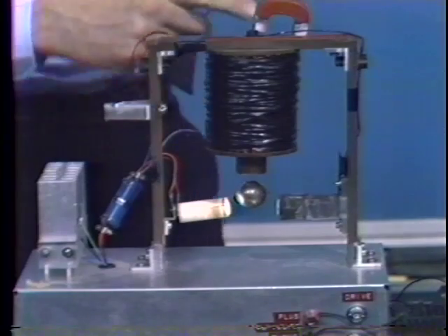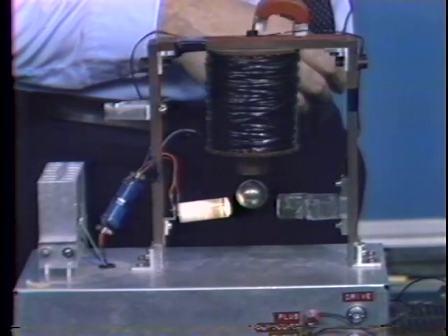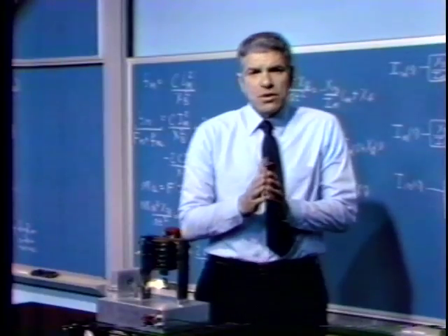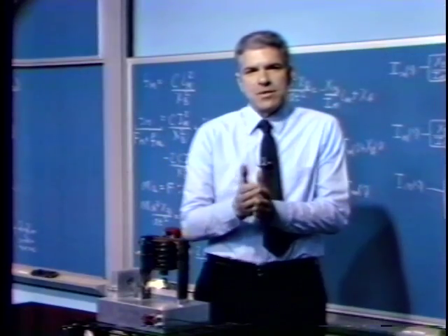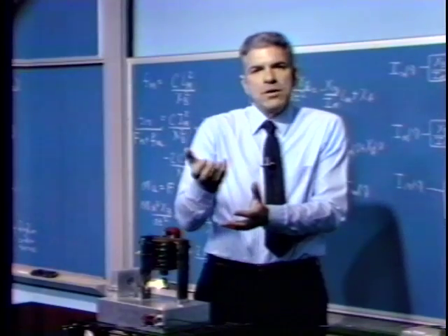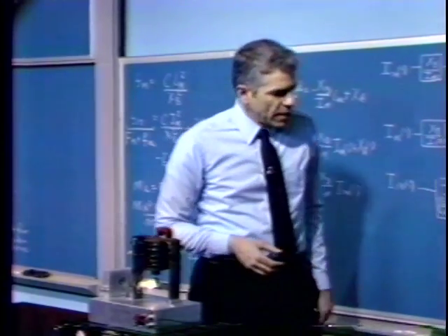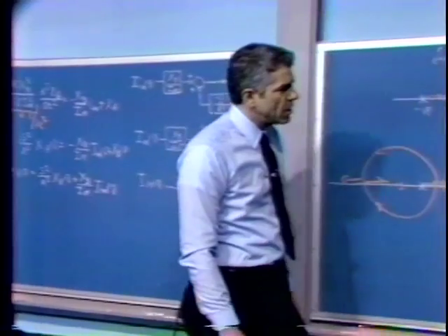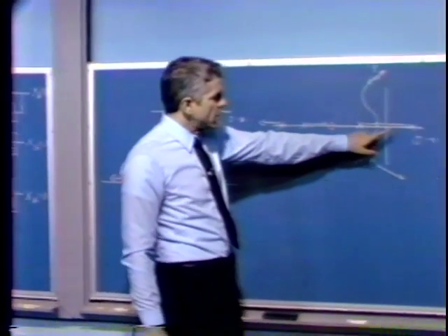And when we do that, there's two modes of behavior while the system's unstable. One is just sort of the ball falls out of the field. It either drops down when we let go of the ball, or it gets pulled up into the magnet. Well, that corresponds to the condition in our root locus diagram where we really don't have enough A naught.